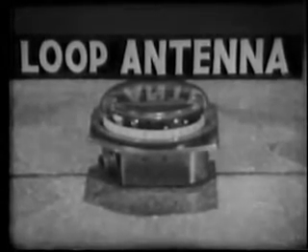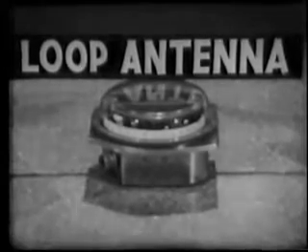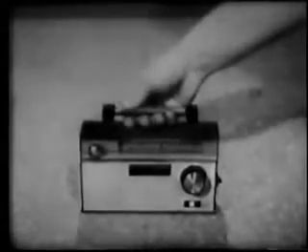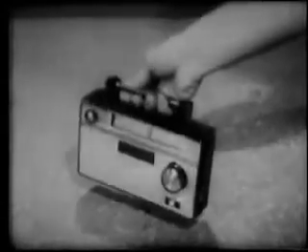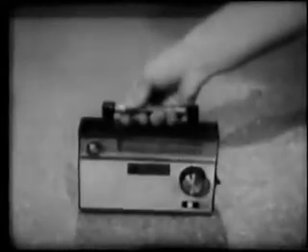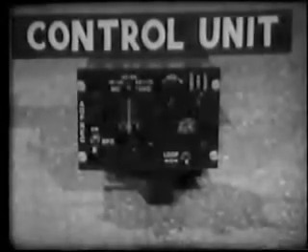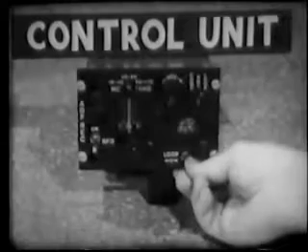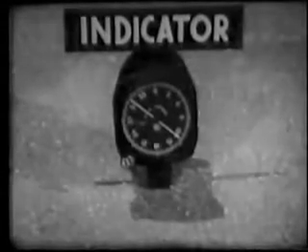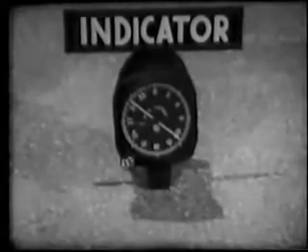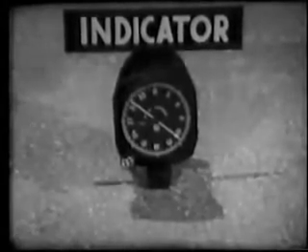You have seen the principle of this antenna in portable radios. When the directional antenna is aligned with the station, the strongest signal is received. When it is perpendicular to the station, the signal will fade out. This is called the null. To use the receiver manually, then, the pilot rotates the loop with a loop drive switch as he listens to changes in the signal. The indicator is connected to the loop and will show the direction to the station when the loop is in the null position.